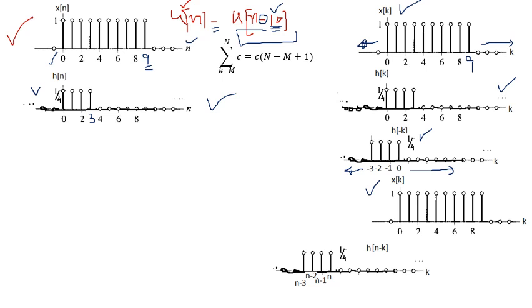Okay, the next step is that we add some value n to the argument of this signal. When the shift is negative, like here the shift is positive, you shift the signal to the right side. If this is negative, then the resulting signal is shifted to the left side. By how much? By a factor of n we shift it. Previously this sample was at 0, now it will be at n, and this one was at minus 1, so now because it's shifted by n, it will be at n minus 1 and so on. I hope this is very clear to you.